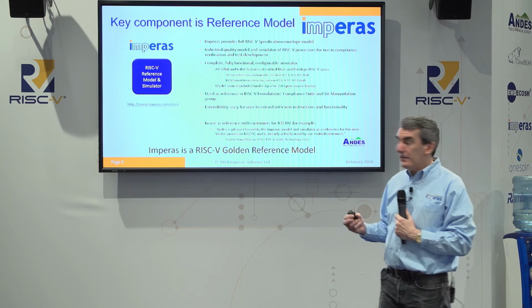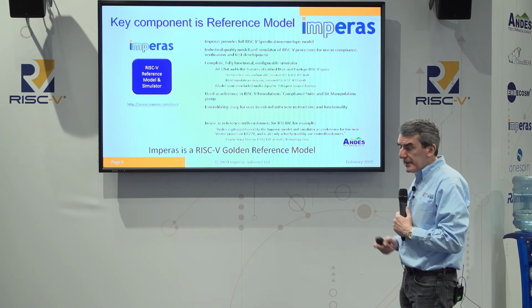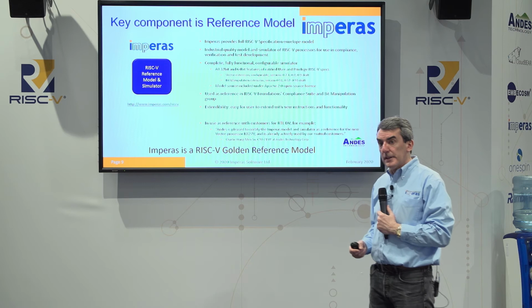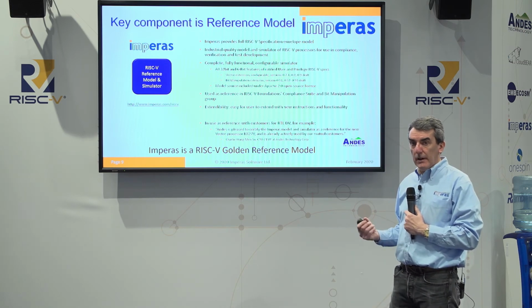Within RISC-V, we developed a reference model. We used this initially with the compliance suite to develop the first generation of test suites that are available on GitHub, to show how you can compare your device and make sure it's fully compliant with the ISA specification. This has now been extended to support the vector extensions and also bit manipulation. And again, it is a reference for the architecture.